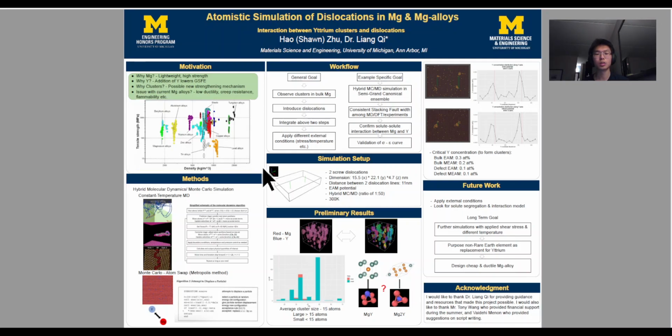I input 2 screw dislocations into the system, and you can see the dimensions there. And I'm using a 300K room temperature condition with an EAM potential. So here are some of the preliminary results that I was able to get from this project.